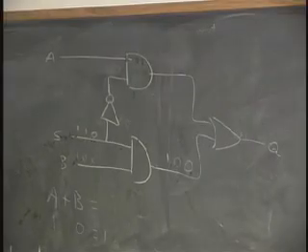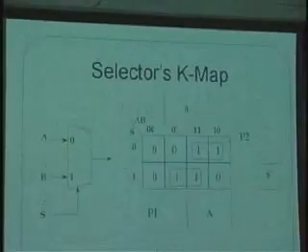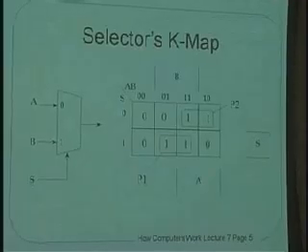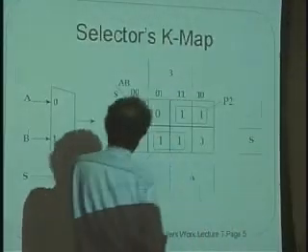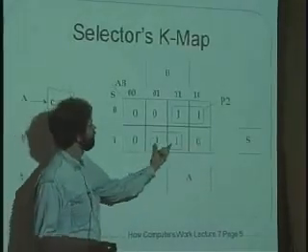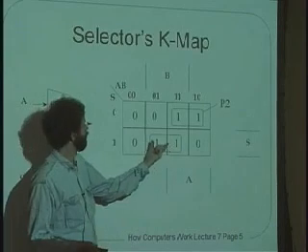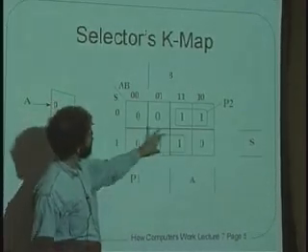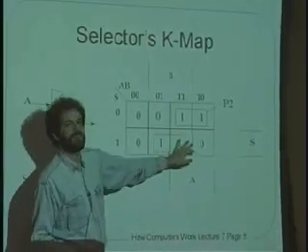When you get a chance, could you go to the previous slide, where we had the K-map up there? Is there any meaning to reading across a row of that Karnaugh map, like one row, 0, 1, 1, 0? Does that stand for something? Sure. It stands for the fact that in these middle two boxes, it's 1, meaning that the output of the selector will be 1 in the cases where S is 1 and B is 1. That's in those two. And in the other two, it's going to be 0.